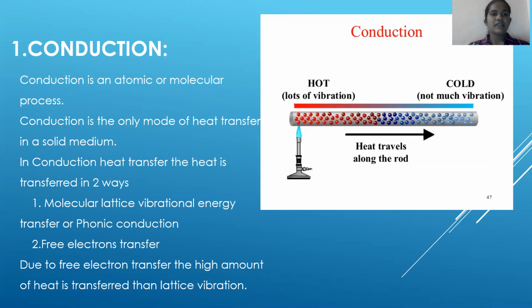Conduction is also known as atomic or molecular process. Conduction is the only mode of heat transfer in a solid medium. Conduction is a process in which heat is exchanged between a hot body and a cold body with physical contact and without displacement of molecules. In conduction, the heat is transferred within a body in two ways: molecular lattice vibrational energy transfer, also known as phononic conduction, and free electrons transfer.